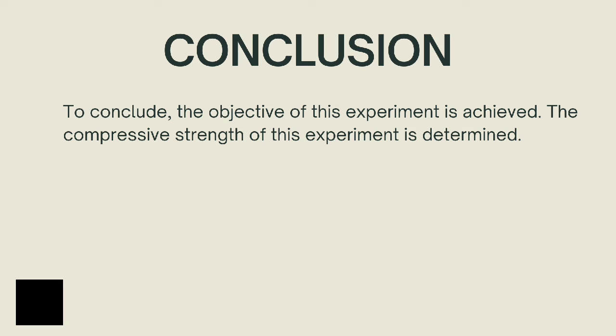There are a few errors that may occur during the experiment which cause the results to be less accurate, such as parallax error that resulted in wrong calculation. After that, the rock sample may not be clamped firmly, which may cause it to move when the load is applied, causing inconsistency in the readings. This precaution must be taken into account in future experiments.